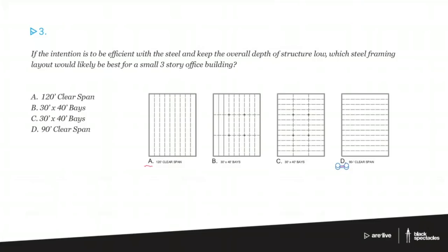You could span 10 feet in steel if you wanted. You could span 50 feet in steel. It's just that you lose the straightforward efficiency once you get lower and higher than these. So that's why, when you look at a steel framing plan, it's pretty typical that the numbers will be in that 35, 40 foot range, because that's where it economically makes the most sense.